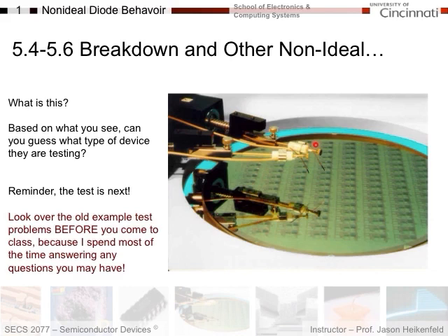But the point is, when you're doing semiconductor work, you don't have these nice packaged chips when you're doing the development of the chips. And so you typically fabricate everything on top of a semiconductor wafer, which you can see here. And if you look, you can see little dies, which are each chipset shown here. And when you want to test these things, you basically bring down these tiny little probes down onto the surface of this. And you're doing all this under a microscope. So you're looking down at this through a microscope. And then you move this back and forth very finely to go from test die to test die to see how your device has worked out.